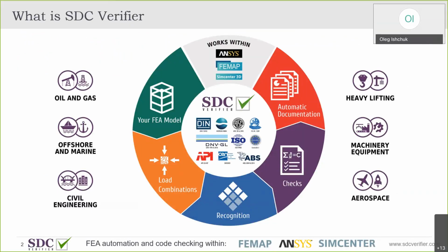So SDC Verifier is a powerful post-processing tool which performs code checking, reporting, load combinations, and some other small features within your FEA model, which is built in Ansys, FEMAP, or SimCenter 3D. So modeling still has to be done by you. And we take your finite element model and results from your finite element model.